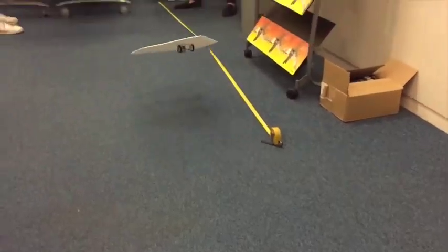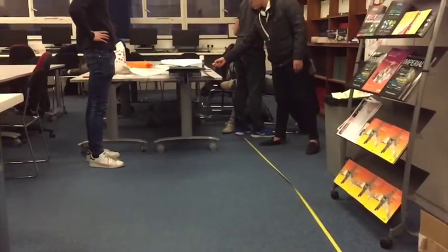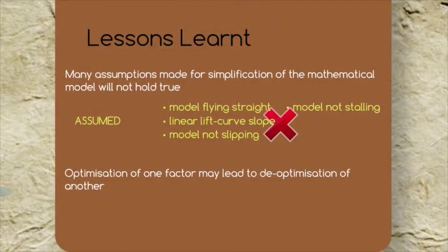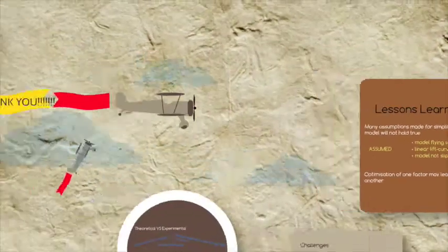To fix this, we shifted the wing mounting position backwards. This, though, caused the aerodynamic balance to go off, compromising the gliding phase. Unfortunately, adding weight to balance the glider was not an option, as we were already close to the weight limit.